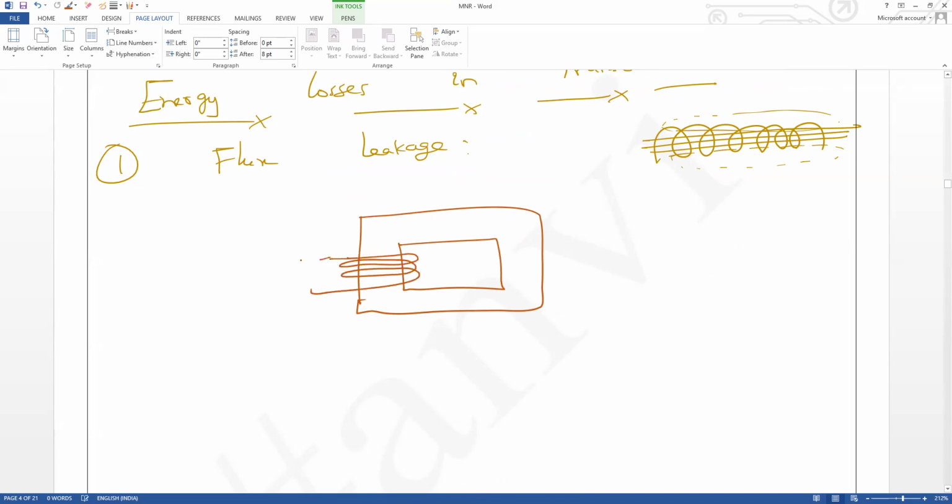That is the cause of power input not being equal to power output. You can check both the coils. What is going to happen? I will take different colors and draw. Inside it is passing, that's fine. Then it goes like this. Solenoid, we all know that. Am I right, everybody? At the end, some flux will be leaking. There is a leakage of flux at the corner. That is the cause of losses of energy.